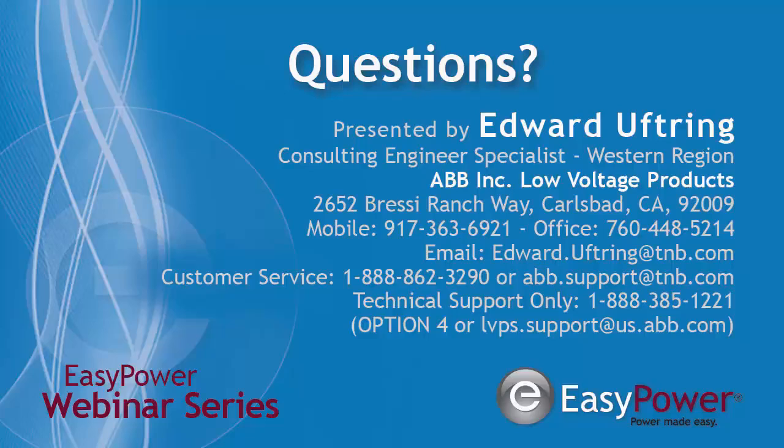What is the typical setting for undervoltage for the trip on main breaker and feeder breaker? I've seen it at 5%, and I've also seen it at 10%. There are some critical power applications, if you're looking at hospitals, where they actually try to dial it down to 1% of the voltage. To me, that gets a little bit hairy, because you could have the switchover happen very fast. You know, a big storm rolls by, you'd see a 1% dip, and then all of a sudden you're tripping. So I would recommend around 5 to 10%.